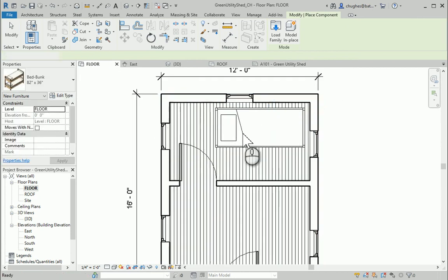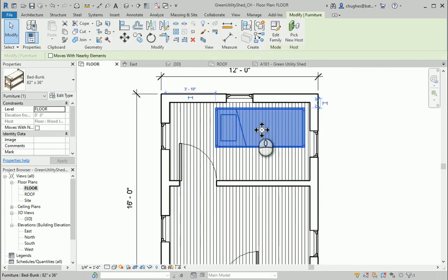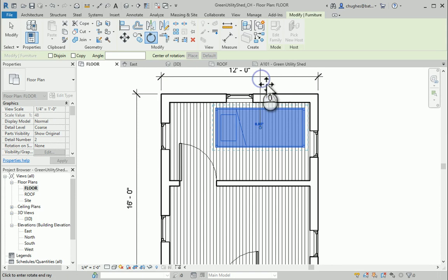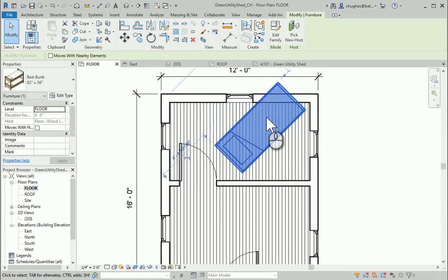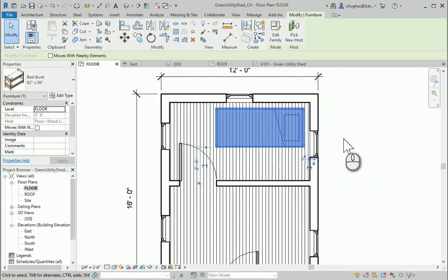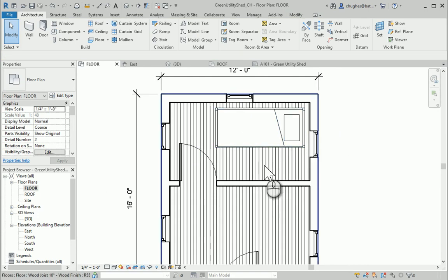After you're done, if you wanted to rotate this or anything, you can select this item. Here's the rotate button. Select rotate, and then if you wanted to turn this at a certain degree, maybe you don't want it facing at 90 on edges or anything like that, that's what you end up seeing there. I'm going to hit Control Z, but you can also hit space bar and that'll flip items around in 90-degree increments.